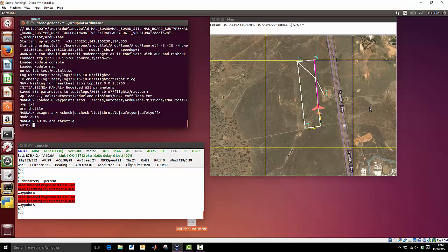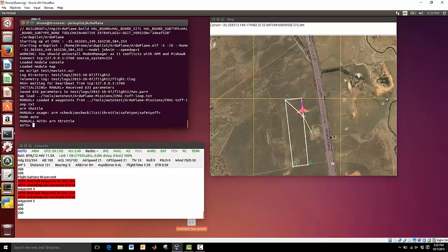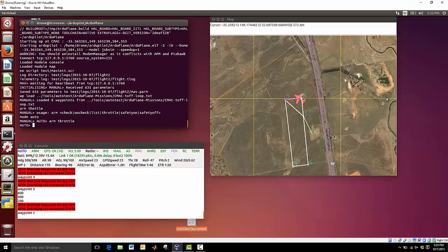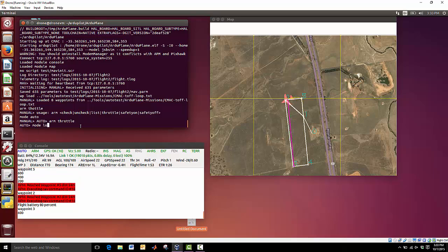It's all on the same machine right now. The ground control station is also acting as the same machine running the drone simulation, the operating system software and the flight simulator software. But we could configure that differently. But even right now, with it all on the same machine, the commands are being simulated using UDP over IP protocol, which is something I've been able to get very successfully to work with this simulation software. In theory, we should be able to use TCP over IP, but I have not yet been able to really get that to work. But the UDP works fine in all modes.